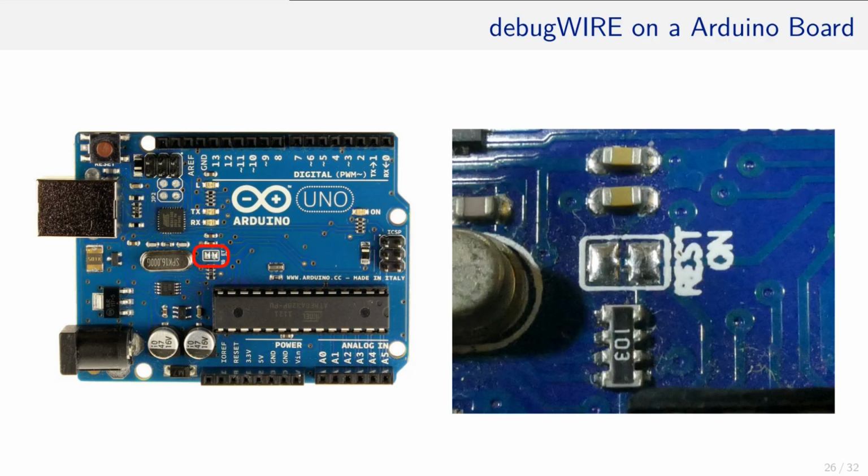But let me show you how it works. If you would like to leave the ATmega whose user program is to be debugged in the Arduino development board, you can do so. However, to be successful, the decoupling capacitor needs to be disconnected from the reset line. To do so, you have to unsolder or cut a link on the Arduino board. Be careful with a knife and avoid cutting any other traces on the board. Since the cut to be made is so small in the demo, I'm therefore using the standalone ATmega from the previous exercises.